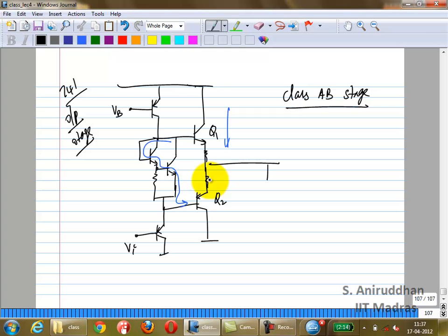If RL is 0, what happens? First of all, PC was a function, the power dissipated on the transistor was a function of RL. Because the transistor will try to force the output to be equal to the input, but that is actually shorted to ground. So it will try to pump a lot of current. And eventually the transistor will burn up.